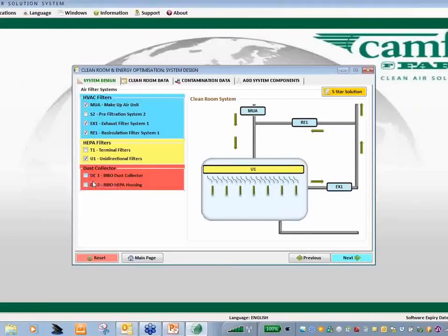Often in a solid dose facility, API, maybe a potent compound facility, there's a dust collector off a tablet press or a tablet coater, and often downstream you have a safety filter, a bag in, bag out HEPA. So we have that option too. One thing we haven't got yet is the lifetime calculations on cartridges within the dust collector, but that's data we're collecting. Once that's done, we'll input it. But at least you have the option of including airflows when you're looking at the design.